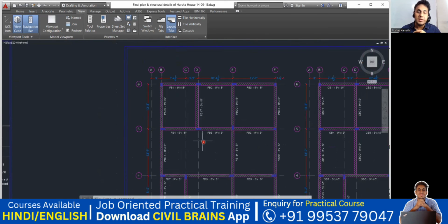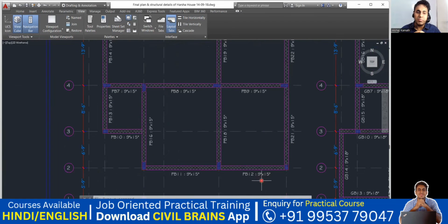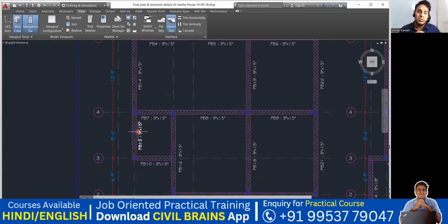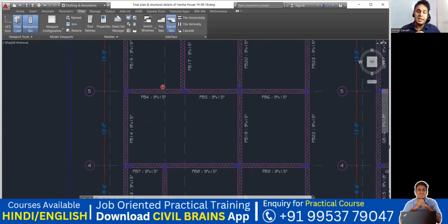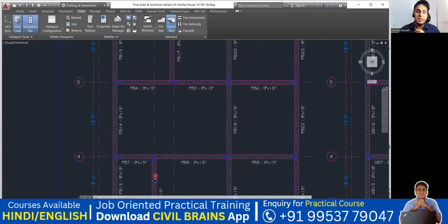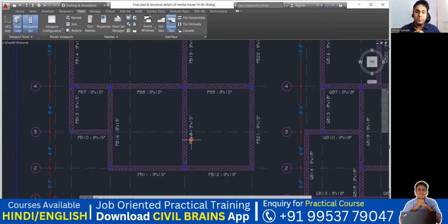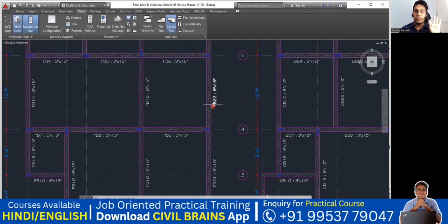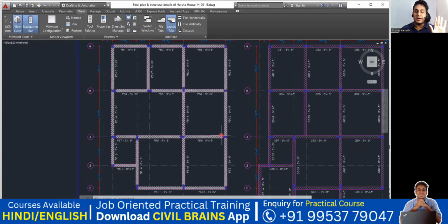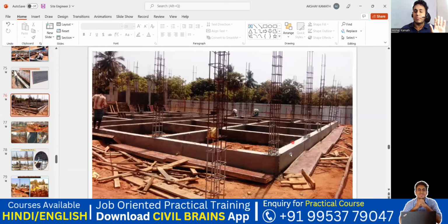Okay. So, what these people have done, we'll see that from where the PB12 ended here. So, where is my PB13? Yeah, it started from here. Good. So, this is PB13. This is PB14. This is PB15. And then this is my PB16. Got it? PB17. And then 18, 19, 20, 21, 22 and 23. Done and dusted. Very simple. So this is how the plinth beam layout has to be understood. And practically when you do the execution, this is how your beams look. Let us say this is my PB1, PB2, PB3, PB4, PB5 and so on.